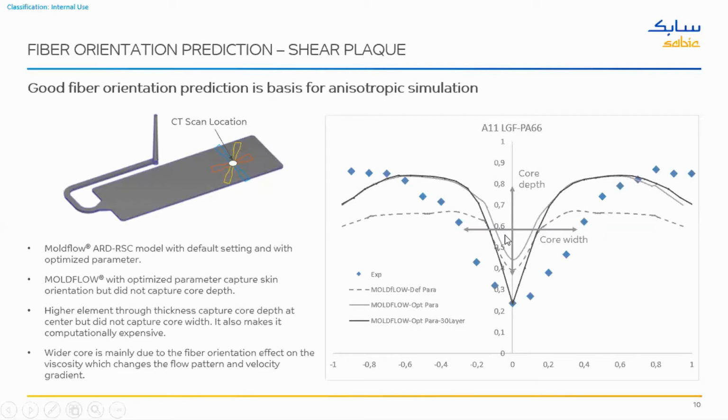Now, some of these factors, during discussion with the Moldflow engineer, they have mentioned that this is something, an effort which is currently ongoing at Moldflow, of improving it, which is essentially how to incorporate the viscosity variation as a function of the fiber in the part, which also varies more when you have higher fiber loading. So that is one of the aspects that needs to be incorporated. But the skin aspect, what we have seen is captured well with the Moldflow simulations.